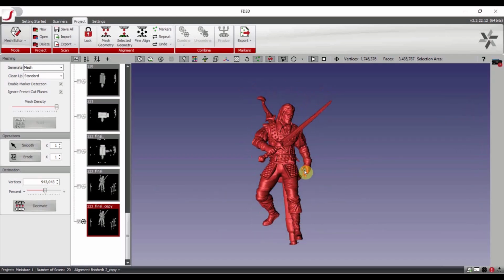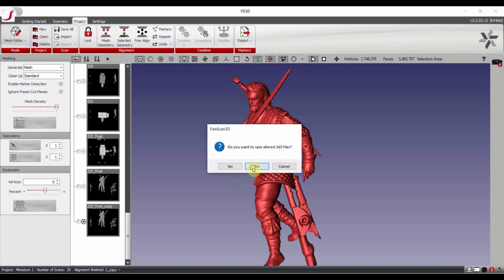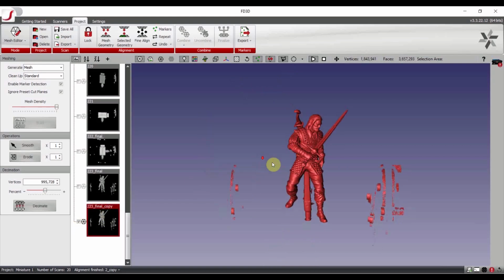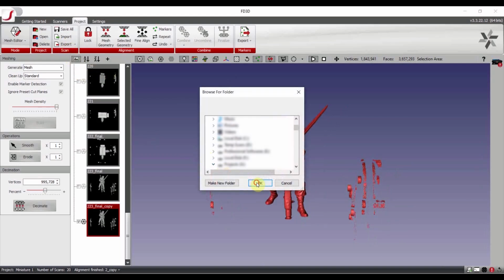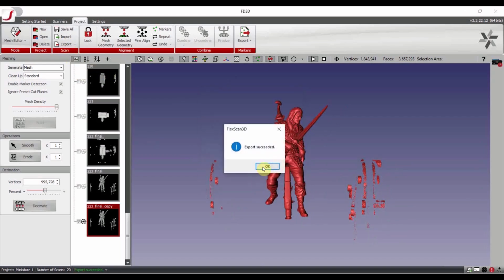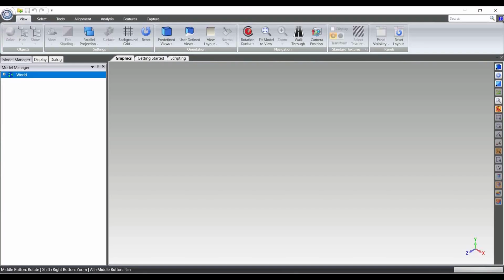But sometimes the shape of the object is so complicated, and the artifacts are distributed between the object elements. So we can use a mesh editor software to remove any floating artifacts from the scan data. Now, as the second solution, I try the Geomagic software.